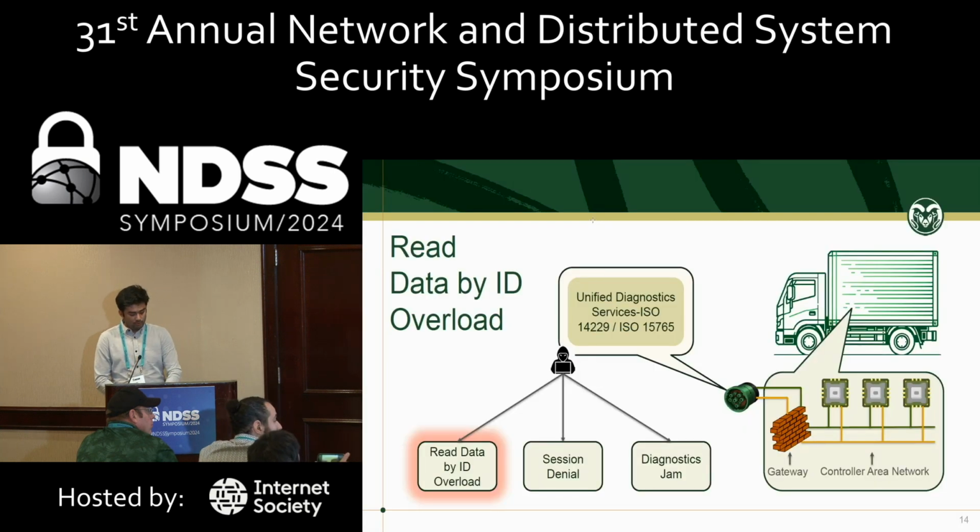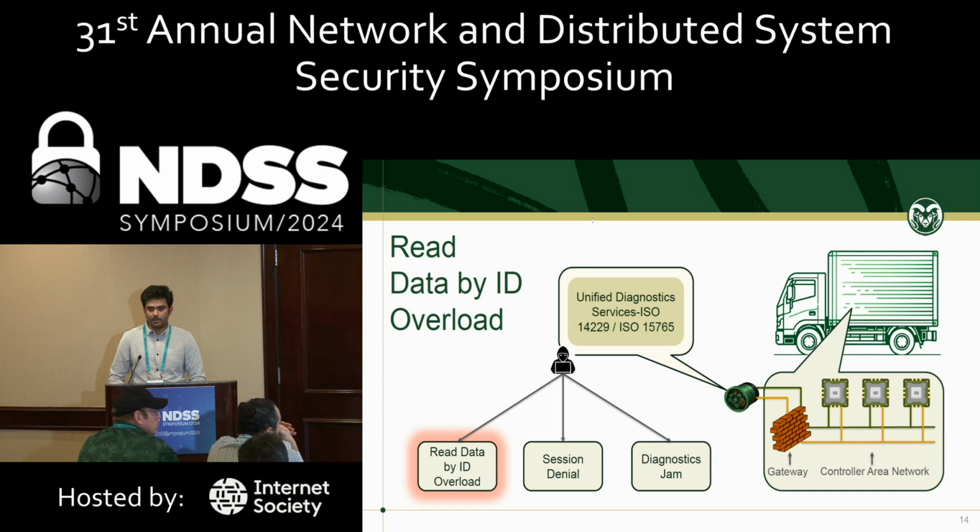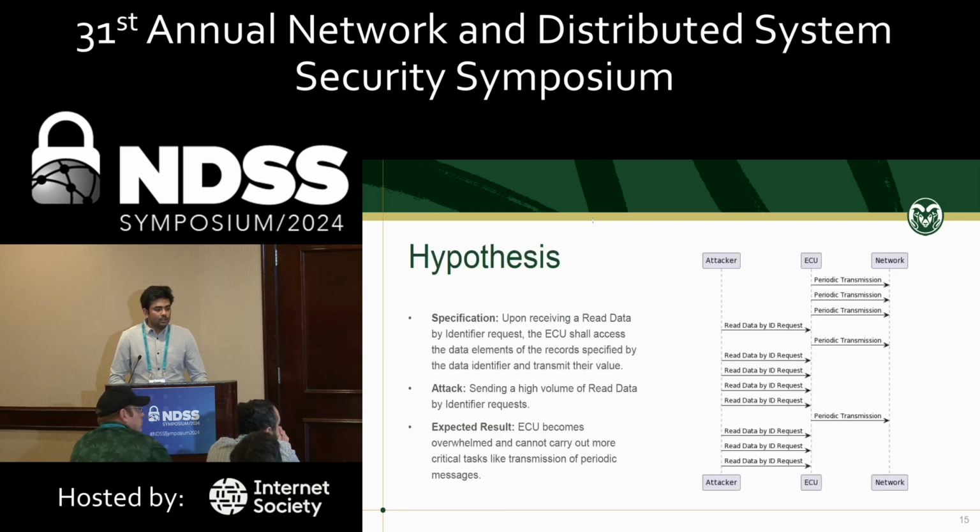Okay, moving on to the 3 attacks that we found on UDS protocol specifications. The first is the read data by ID attack. All these are denial of service attacks in some form or the other. The UDS 14229 specification states that when a read data by ID request is sent, the ECU must respond, and that it should access its data elements and respond with a specified value.